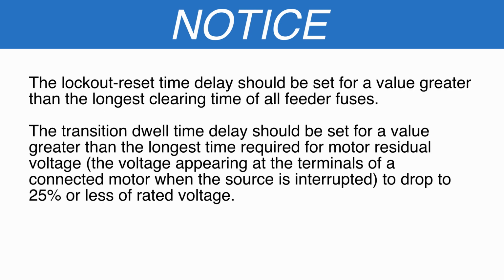The lockout reset time delay should be set for a value greater than the longest clearing time of all feeder fuses. The transition dwell time delay should be set for a value greater than the longest time required for motor residual voltage, the voltage appearing at the terminals of a connected motor when the source is interrupted, to drop to 25% or less of rated voltage.